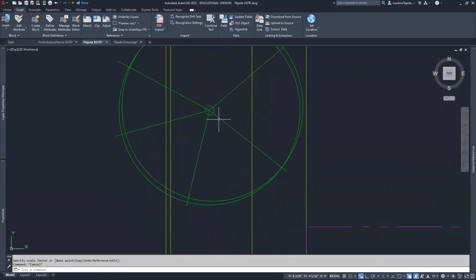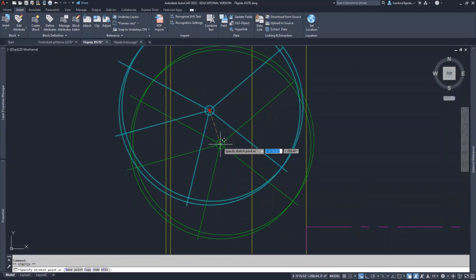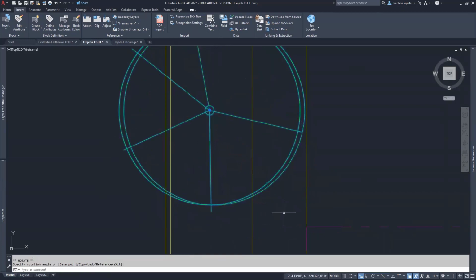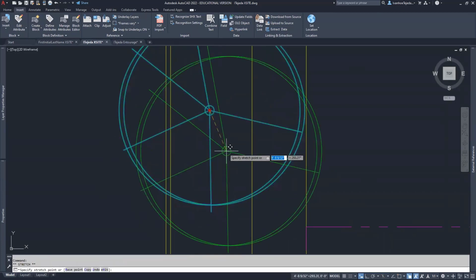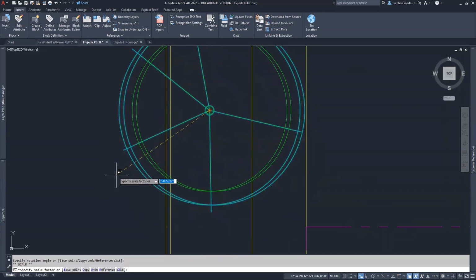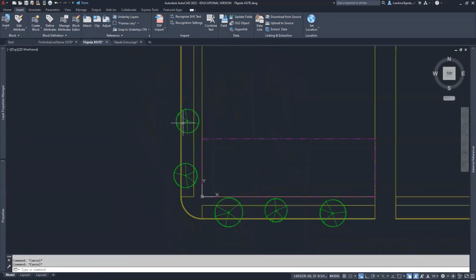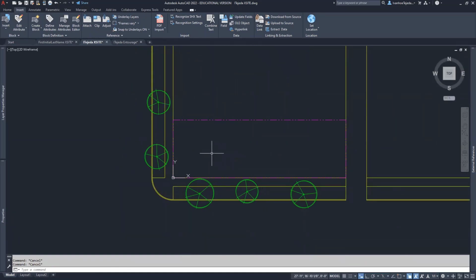This one here. Zooming in, selecting, clicking on that insertion point, tapping the space bar until I see the rotate option. I'll rotate it down this way, click on that insertion point again, tap the space bar until I have the scale option. And I'll scale this one down a bit also like that. And then tap the escape key and I'm all set. And notice it's the same symbol, but I was able to make these modifications and now they look slightly different, different sizes, different rotations. So it helps give it that organic look that we need.